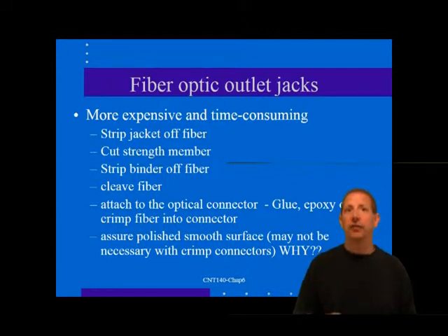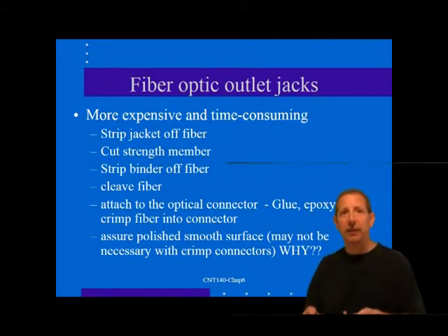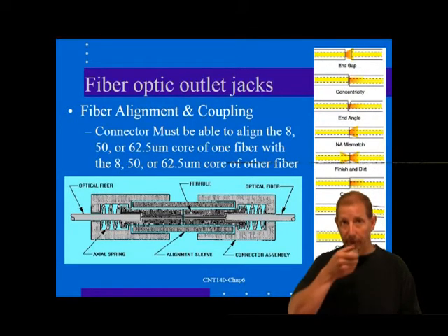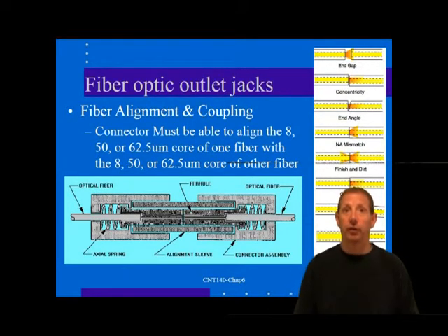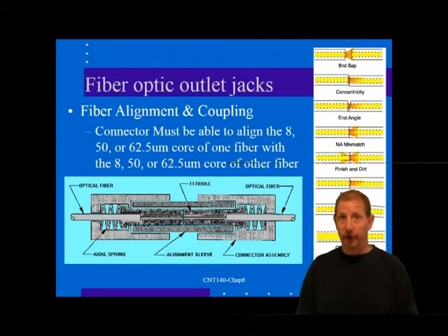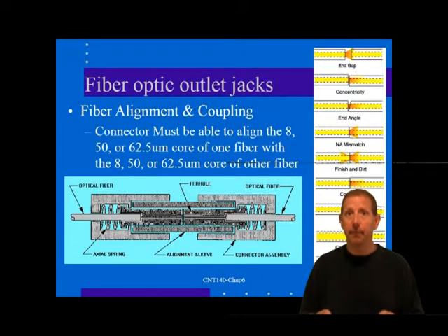Finally, the connectorized fiber end must be carefully polished to a smooth surface so that the light entering or exiting the fiber is not bent off the axis. The polishing step is not required for quick termination connectors, however. In order for light to couple properly between the connectors, the internal fibers must be carefully aligned and placed virtually in contact by the coupling device.